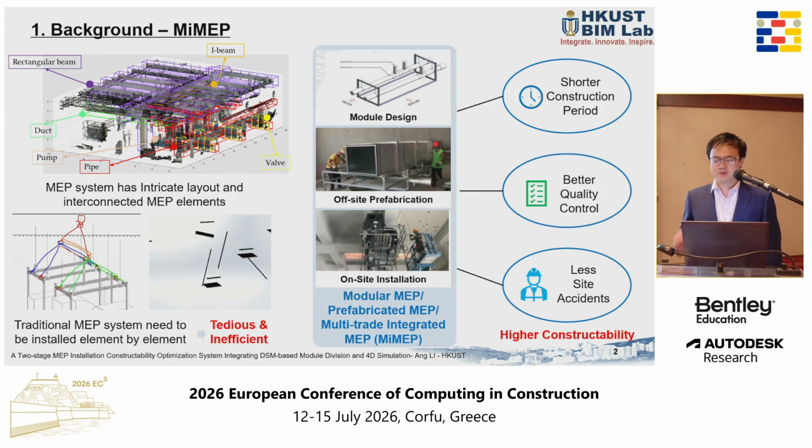Traditional piece-by-piece MEP installation is inefficient and risky due to the highly complex layout of the MEP design, as the figure shows. To solve this, the industry is shifting to modular MEP or multi-trade integrated MEP. By prefabricating module designs offsite and bringing them to on-site installation, we can achieve higher quality, shorter construction period, and fewer accidents. In other words, we have higher constructability of modular MEP.